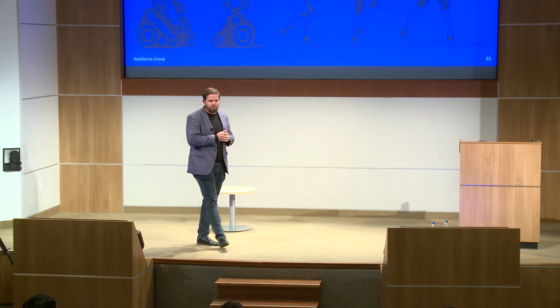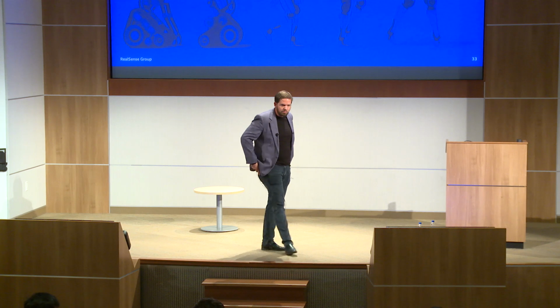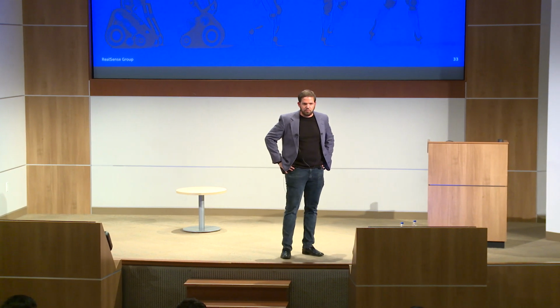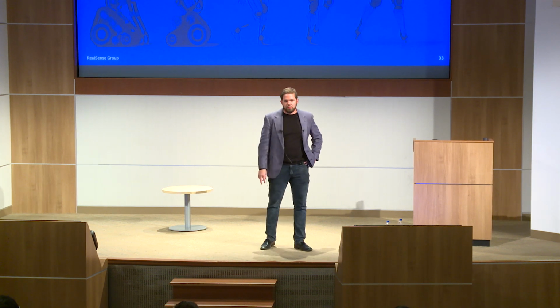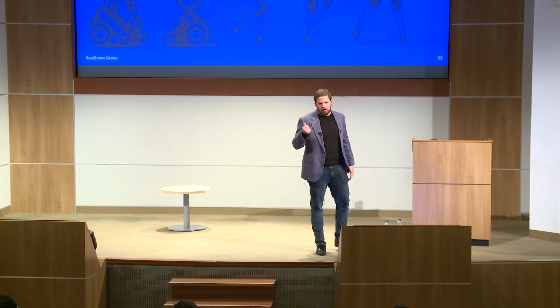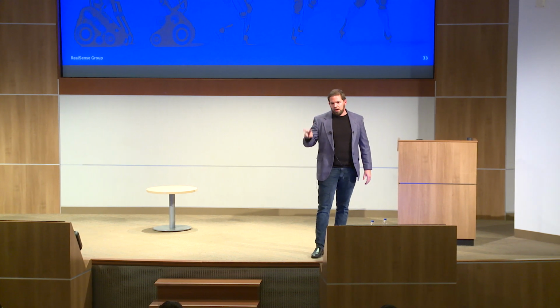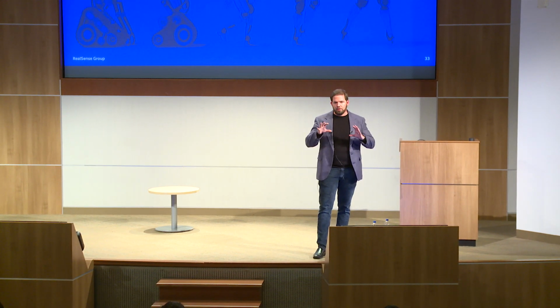I have two questions about calibration. For your 3D robot, I saw you have a depth camera and a tracking camera. Do you calibrate them together? Yes, they have been calibrated with respect to each other as well, using all five images. We used the two IR and the RGB from the depth camera, and the two fisheye, and solved that calibration problem.